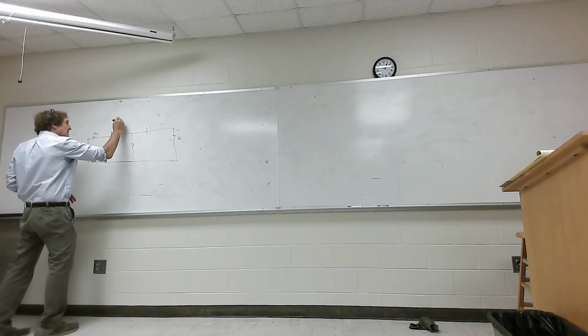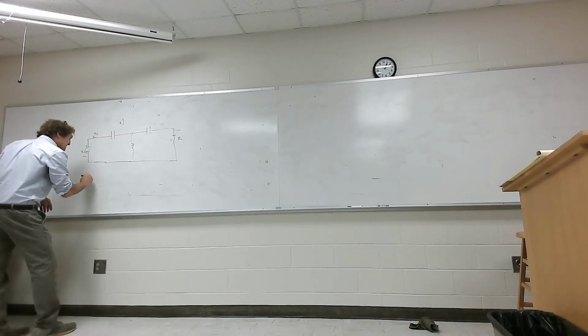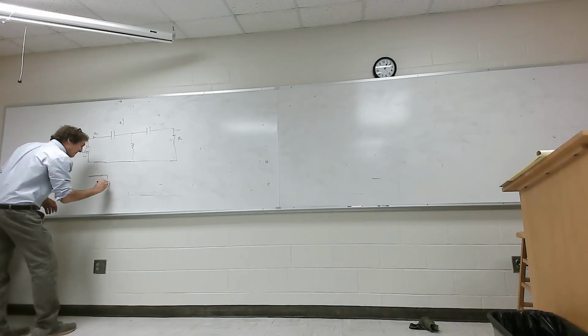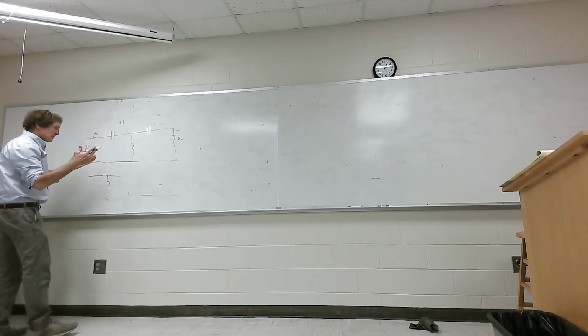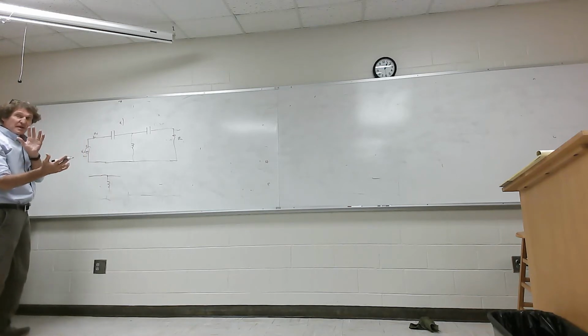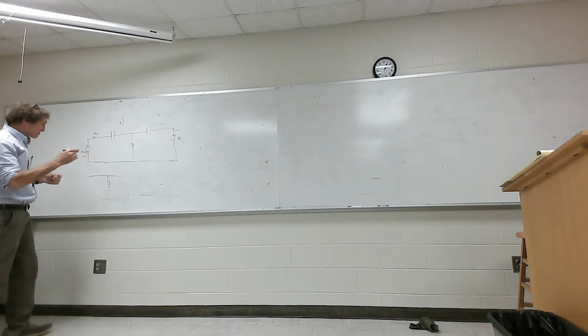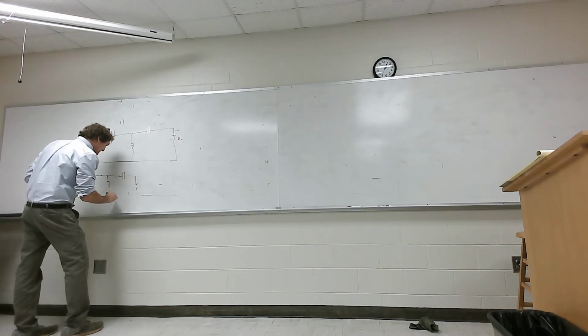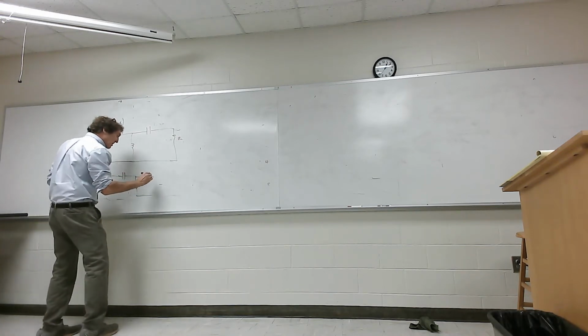Now, next, that's one. We'll call this A. And for B, it could be this way. If you wanted a high pass filter, you could have an inductor here. This is going to be the pi filter, but now where the inductor and capacitors where you exchange the places. This will become a capacitor, and this is an inductor. I have one comment about this.